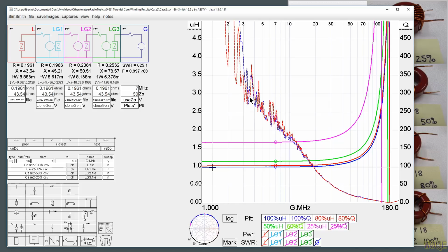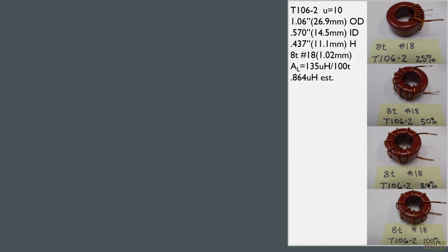that accurately. But we do see when the Qs get lower, like 60%, that looks to be a little bit lower, maybe, not much. 25% is just different. It's hard to say. None of these have bad Qs. So I wouldn't use Q as a measurement for whether the inductor is better or worse. I would probably use which one is easiest to mount. And if that's the case, I would use this one or this one.